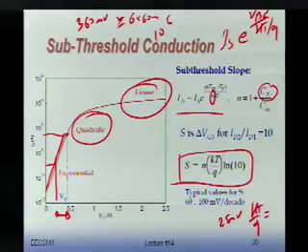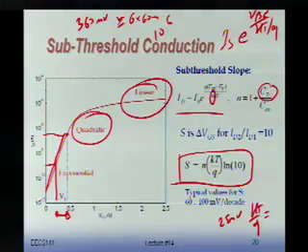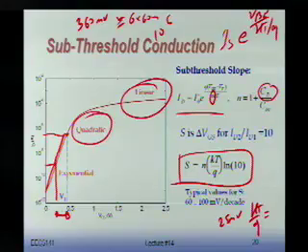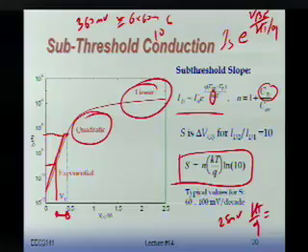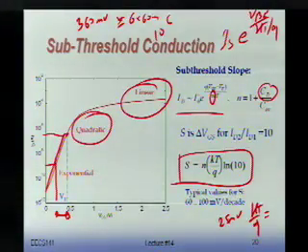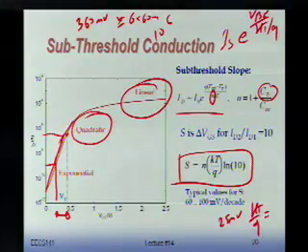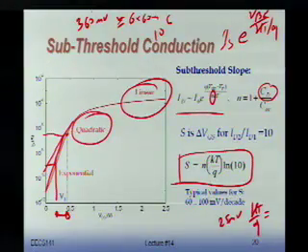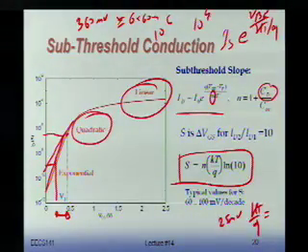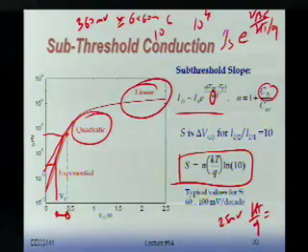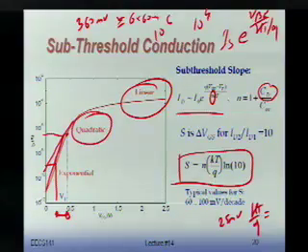Unfortunately, not a single MOS transistor has a subthreshold slope of 60 millivolt. In reality, there's always this N factor. So N varying between 1 and 2, as I mentioned. Typical numbers are about 80 millivolts per decade to 90 millivolts per decade. So the slope is not going to be very steep. It's going to be a little bit more like this as a result. So if I now take, let's say, 90 millivolt, I get only a factor of 10 to the 4th reduction in current. Right, this 4 times 90 is 10 to the 4th reduction. That's a factor of 100 more leakage current.